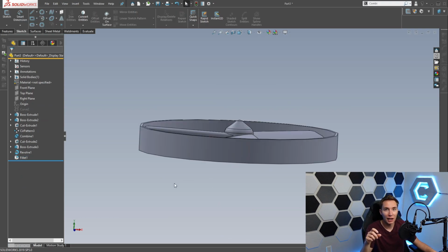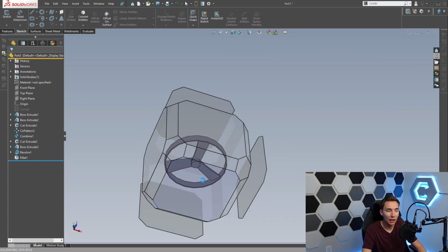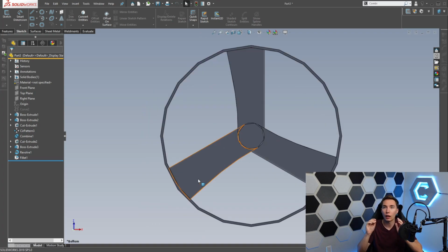The last thing to design was where the key shaft was gonna go into the bottom that attaches to the die grinder. So this turned out to be the hardest part and the most trial and error. It's because you need enough friction that the top stays on and gets up to a high enough speed that it produces lots of lift. But it can't be so tight that it doesn't release at all from the die grinder. So it's a lot of trial and error, and I still need to work on this part in order to get it to launch at the right speed.